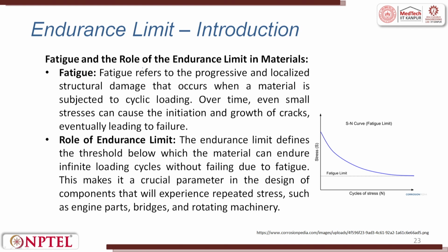Fatigue and the role of the endurance limit in material. Fatigue refers to a progressive and localized structural damage that occurs when a material is subjected to cyclic loading. Over time, even small stress can cause the initiation and growth of crack, eventually leading to failure.